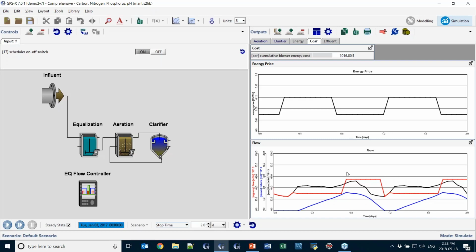Essentially, we're just taking that and moving it over here and doing it during a time when the energy is less. So we pumped all that stuff out. You can see the volume returns to 0, and we did that pretty quickly, to be honest. And then it's empty again, and then we repeat starting over again the next day. So all we were doing really is holding back this amount of flow, the difference, that little area between these two lines here, and then we're pushing it over onto the time when the energy was cheaper.